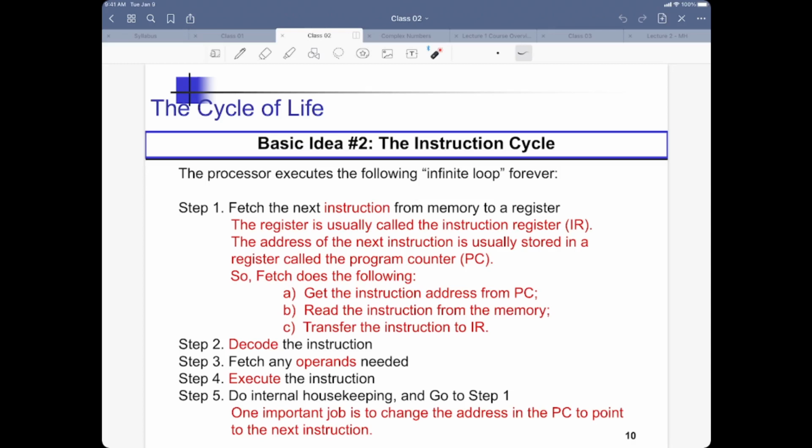Right? I'm executing instructions in this part of the memory, and then I suddenly want to branch off, maybe due to some condition satisfying or not satisfying. I may want to branch off to another section in my memory. Essentially, I need to play around with the contents of the program counter in order for me to perform that branch, right?